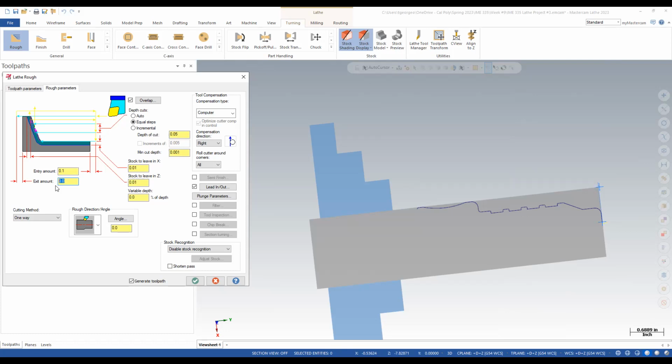Why would I want to maybe do that? For the part off tool, remember we talked about that? How thick is that part off tool? 1/8 of an inch. If you look at your tool 4, it says 0.125 inch carbide part off tool. So there's a 25 thou chamfer on the back too. You see that we didn't really grab on the line right there. So let's add that chamfer and let's add the part off tool. Let's go 150 back farther. Cool. Good. So we put 0.150.